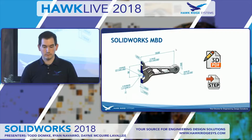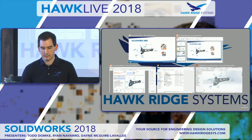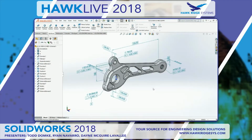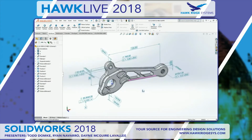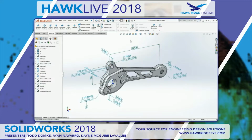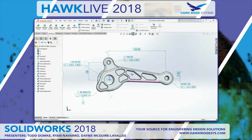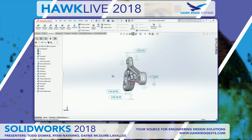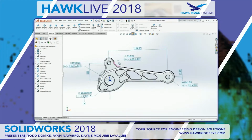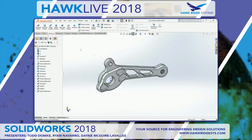And I just wanted to give a quick look at what MBD looks like inside the software and then what the output looks like. So within the software here, I can have a whole bunch of DimExpert dimensions loaded up. If it looks kind of cluttered, they have this nice dynamic annotation view that makes it so just when you rotate to that particular view, those dimensions show up. Okay, and it also aids you with tolerancing too. It'll show us previews of tolerances that are yet to be defined potentially.